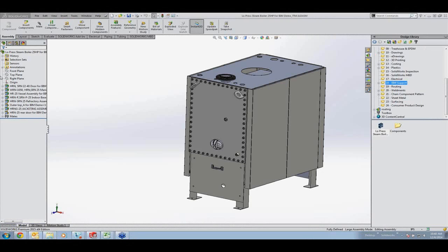All right, looks good. I'm going to create a new weld path here. This also supports faces that might have more than one intersection. In this case here, it has 3 intersections. Also make complex weld paths for corners and sheet metal parts by selecting a face and an edge. Looks good there.